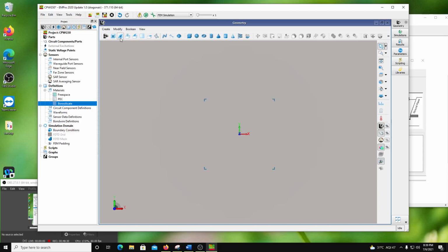Or you can do a 2D drawing and then revolve it, rather than extruding in the vertical direction. You can also take an already existing body, take a face of the body, and extrude something from there, or revolve something from the face of a body.